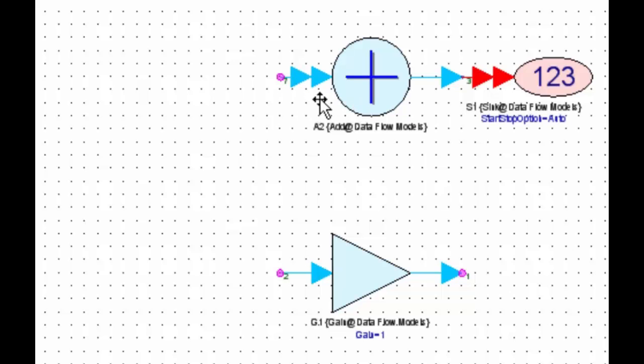multi-port or multi-input part. The difference basically between these is in a single input part, as the name implies, only one signal or one net name is valid at the input pin of this type of component, whereas in a multi-port or multi-input part, the input will actually expand to the number of inputs that are connected to it.